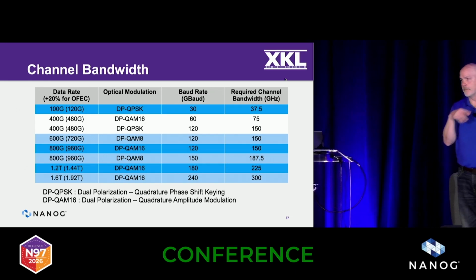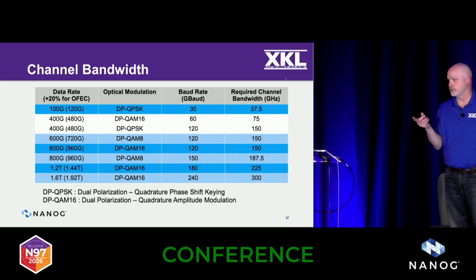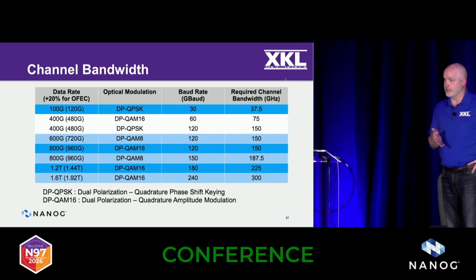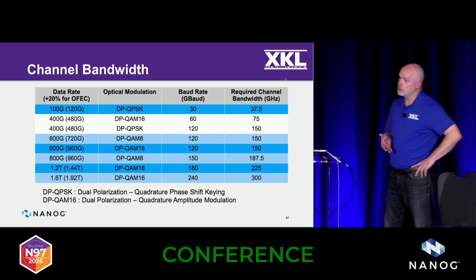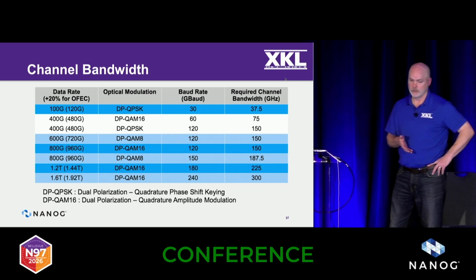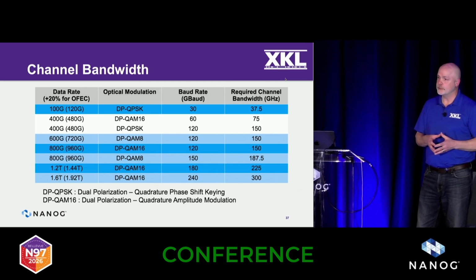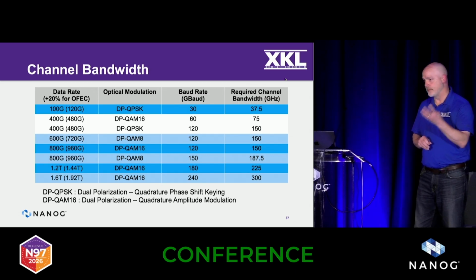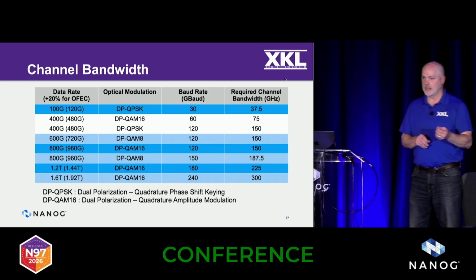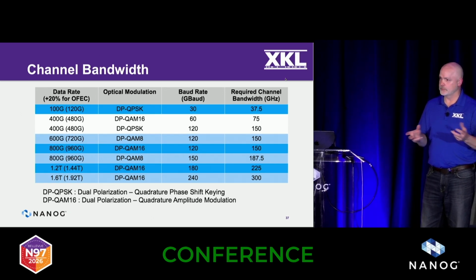And again, I'm going to tie all these things in later when we talk about the filters, spectral efficiency, et cetera. In today's generation of 400 gig, I can now do that with a QPSK modulation scheme. So that's an advancement for noise and reach, but it's a disadvantage when it comes to the bandwidth that is required to transmit that signal because the baud rate is double. So in a QAM 16, that's 4 bits per symbol. In a QPSK, it's 2 bits per symbol.